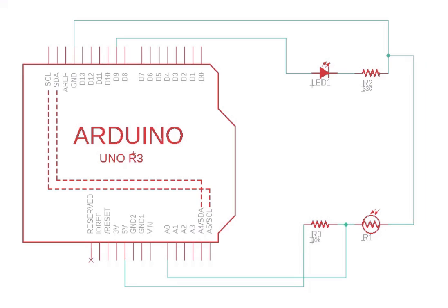So now as the photoresistor gets more and more light on it, it's going to approach no resistance at all. So when there's a whole bunch of light shining on this photoresistor in this configuration, A0 is going to be reading ground. And as less and less light shines on that photoresistor, it's going to start having a resistance, and so the voltage here will rise.